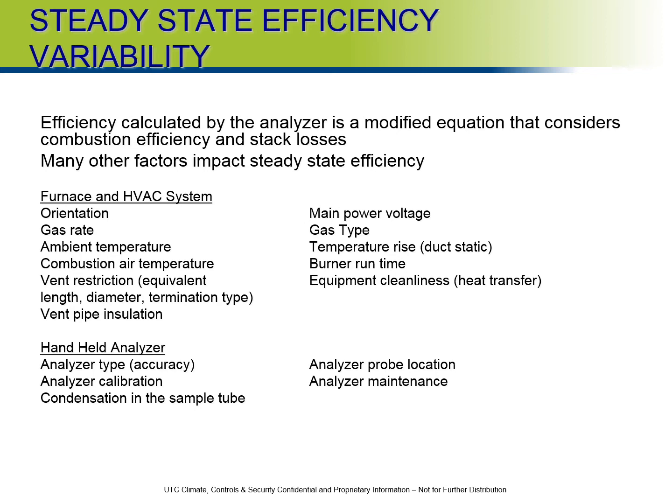And then also, last but not least, we're talking about equipment cleanliness. How often is the equipment serviced? This directly impacts the heat transfer within the system. Most of our equipment is doing heat transfer through some kind of metal, and if that metal gets dirty or has any kind of buildup or film, this also directly impacts the equipment and the efficiency of the equipment.